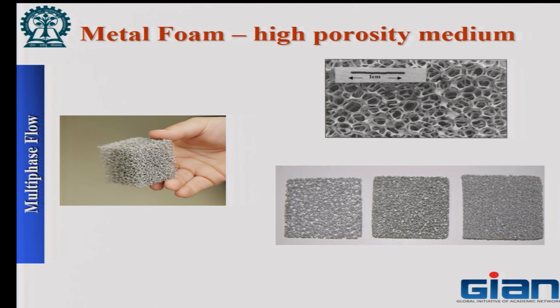Now, what is the most optimal configuration? We really do not know, but some of the experiments that have been done before suggest that this does help in increasing the critical heat flux as well compared to a flat surface. How will the boiling curve exactly look like? Some people have reported that, but it is definitely a function of the materials, the fluid, etc. So, Kaushik, who is my student, this is a part of his PhD thesis. So, hopefully, how does the boiling curve look like as a function of porosity and pore size? Maybe 2 years down the road we will have a better answer.